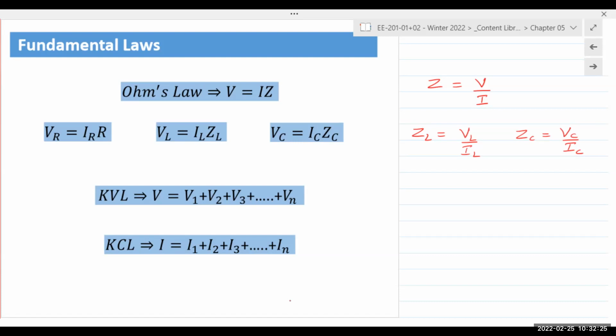But if you take those voltages and add them up, KVL would not work, because when we take a meter and we measure the voltages, what are we doing? All we measure are the magnitudes. We don't get any information about the phase angle. So if you simply take those measured values and add them up, like VR plus VL plus VC, KVL would not work. We need to take phase angles into account, and hence the complex vector representation. If we have the phase angles, then KVL would work. And we can try that out with any problem that we'll solve.